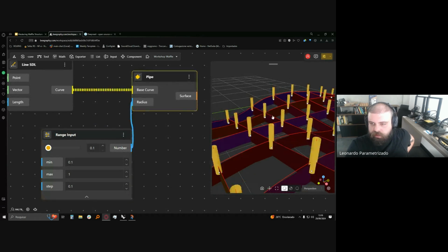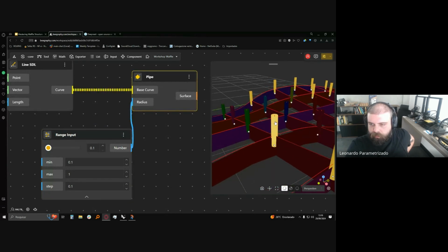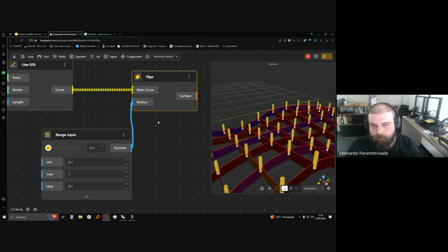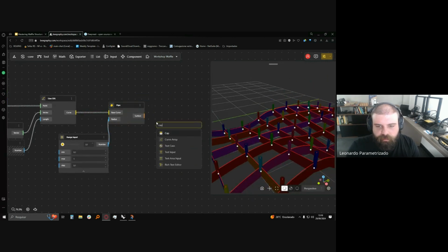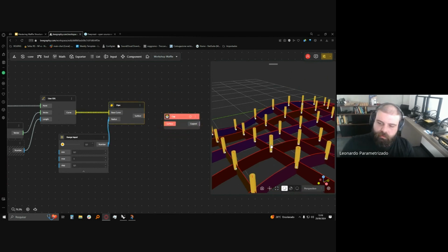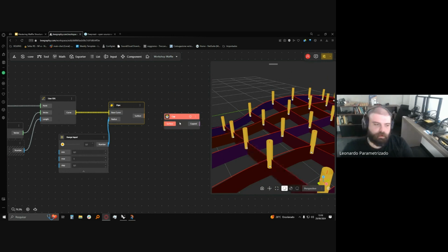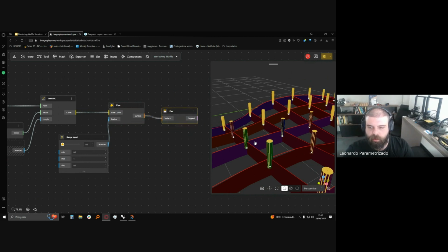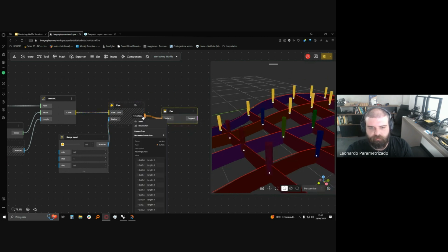And as you guys can see, now we have a pipe here in our 3D. The only thing is that for us to subtract this pipe from this surface, we need the object to be closed. So I'll be using a cap just to close this pipe. Now it's like a solid. Okay, this is a surface. Now this is a solid. Okay, this is important.